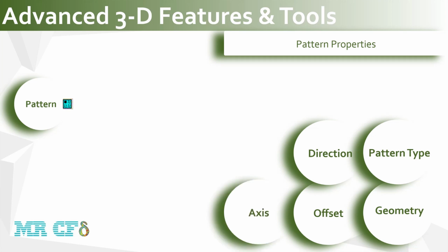Axis, the rotation axis for a circular pattern. The axis can be a direction reference selected from a plane, 2D sketch edge, 3D model edge, face, or 2 points. Angle, the rotation angle for a circular pattern. This is the angle between each instance of the pattern.